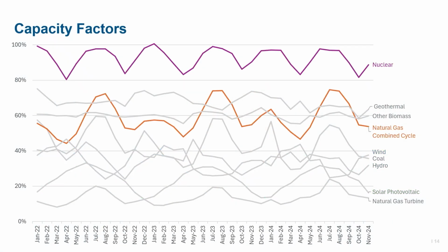We will discuss consumer cost impacts of this challenge later in the ENL. Notice also that non-dispatchable resources, such as nuclear plants and natural gas combined cycle plants, have higher capacity factors. Remember, non-dispatchable resources can't easily be turned on and off, and so utilities tend to size them for minimum load so that they can run almost all the time. A power plant that's intended to run almost all the time, meeting minimum grid load, is called a baseload plant. Some resources that are dispatchable are still often used for baseload generation, such as geothermal and biomass.